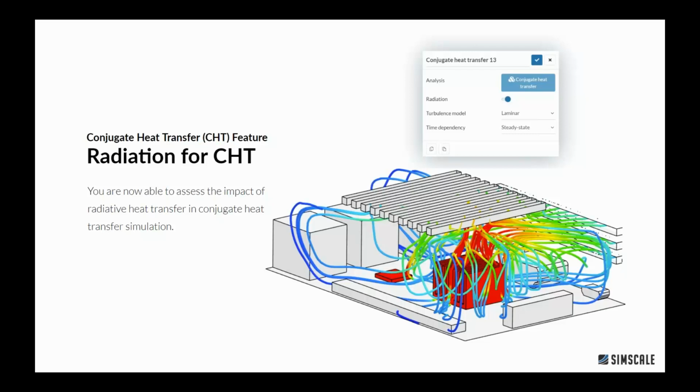And we've decided to add this because where higher temperatures are involved, this becomes very necessary. So if you're working with an application of more than 70 degrees Celsius, radiation starts to be a very significant factor. And you can see a difference of up to 10-15% in the results, really. We don't have a project right now to discuss on this because it's quite new.